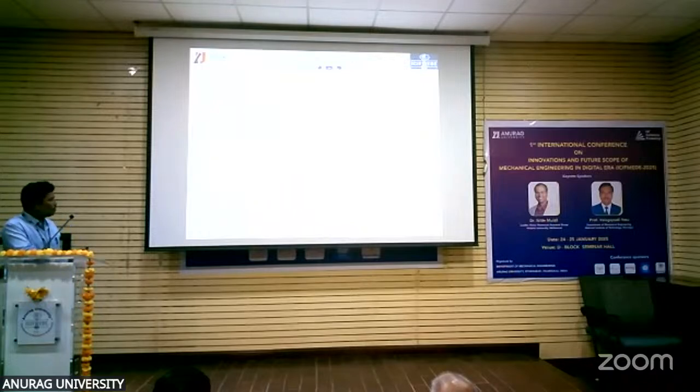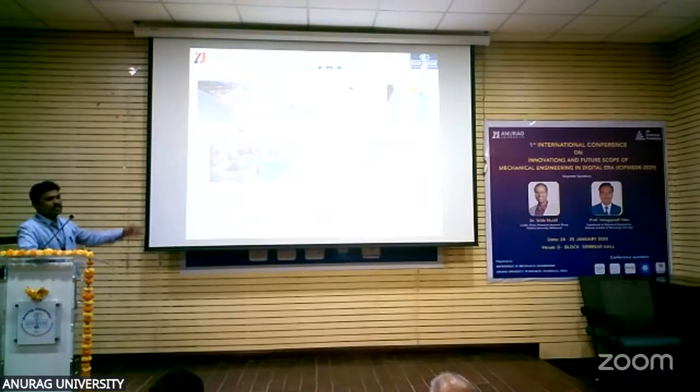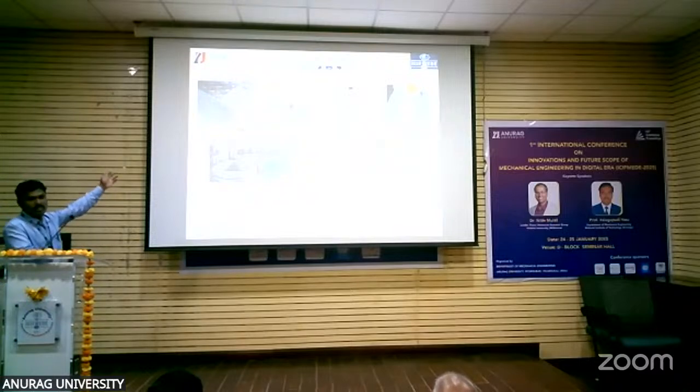Then coming to the steel, H13 is a hard tool steel used for making parts that withstand high temperature and abrasion. It is used in a variety of applications including hot work tools, extrusion tools, and plastic molds. The main properties of H13 steel are high hardness, toughness, and resistance to thermal fatigue cracks. These are some applications for the alloy and steel. In construction, aluminum is mostly used, and alloying also increases the strength of the material. That's why it is mostly used, because of the corrosion resistance.